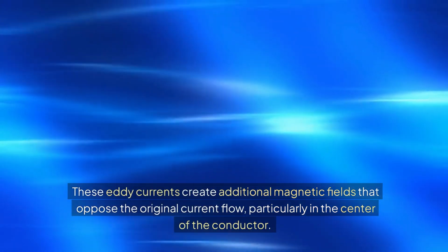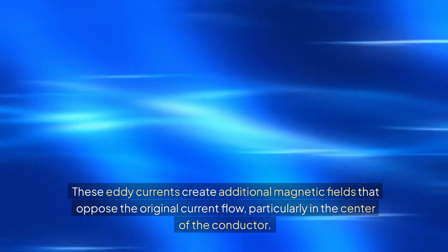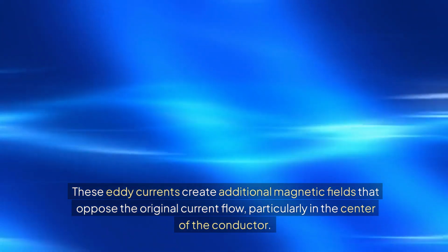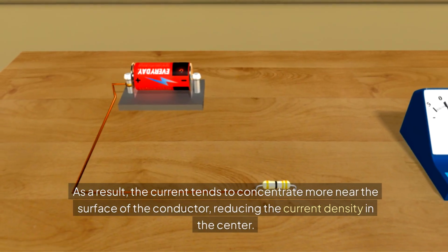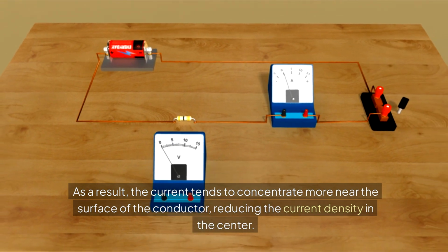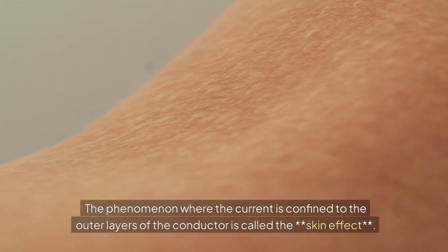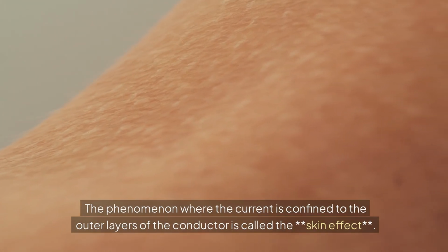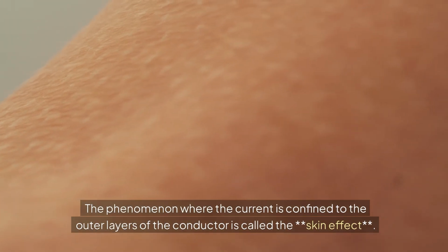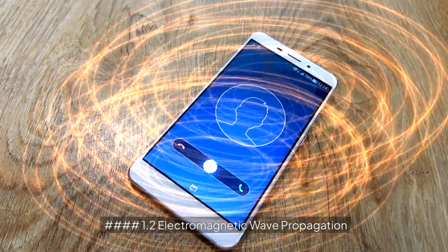These eddy currents create additional magnetic fields that oppose the original current flow, particularly in the center of the conductor. As a result, the current tends to concentrate more near the surface of the conductor, reducing the current density in the center. The phenomenon where the current is confined to the outer layers of the conductor is called the skin effect.